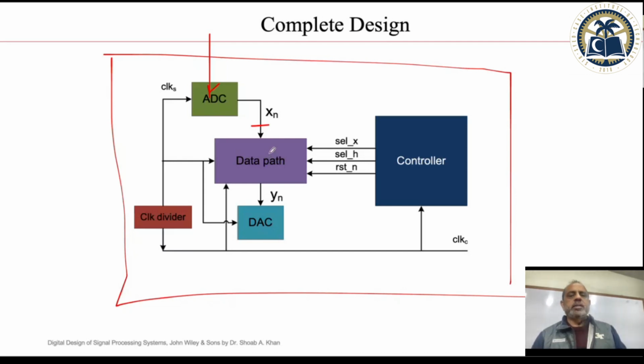And if it is a real-time system, you've got to make sure that you can process these frames, like say 60 frames of high definition coming into your system. You've got to process them in real time. That will tell you how much budget you have to do the processing, because you cannot just lose data. So it comes to the data path, and then sometimes you have to play that back also. If you're doing object recognition, for example, you have to play that back to a DAC converter.